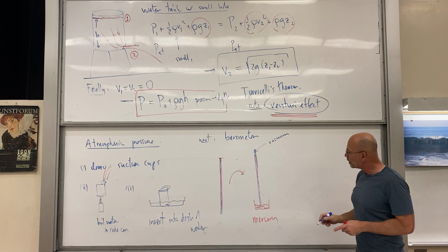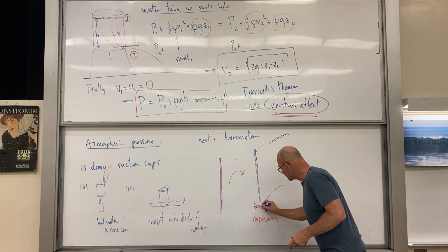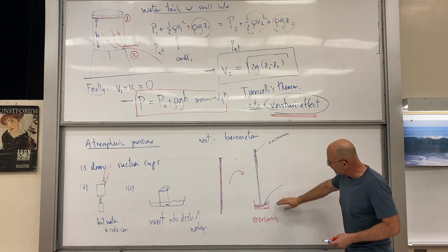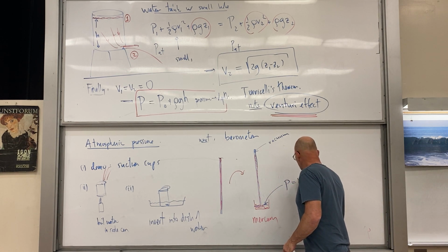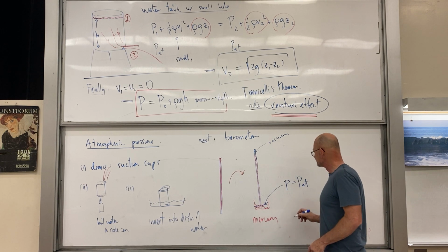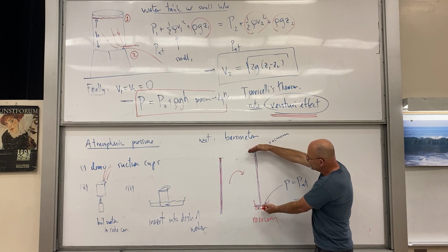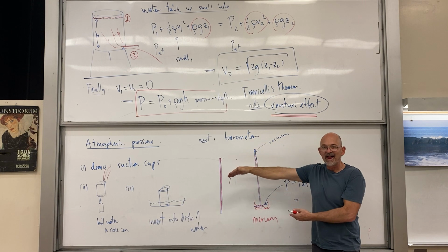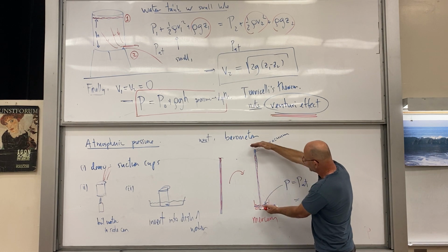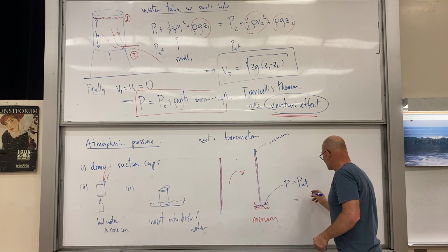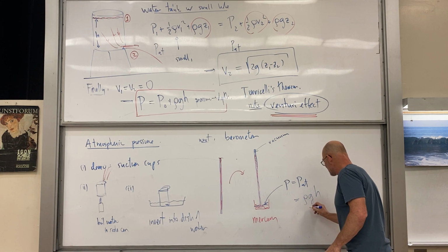Vacuum, and then you argue that the pressure on the fluid outside the capillary, P equals atmospheric pressure, is equal to density times g times h of that column. Just the pressure depth formula, except in terms of that column. So P atmospheric equals rho g h.